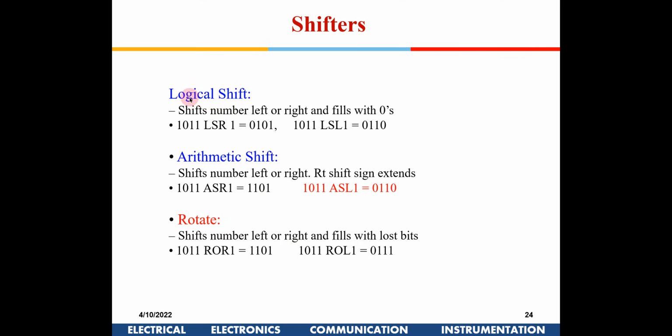Okay, so you can have a logical shift. Now if you see here, a logical shift right. What it is doing is you have shifted this data towards the right, so the rightmost data has been left out. Since it's a logical shift, from the MSB side, which is now vacated, I have put a 0 here. Whenever I say logical shift, whatever vacancy is created, there I put a 0. So this is logical shift left here. So 1011. This 1 indicates that it shifts by 1 bit.